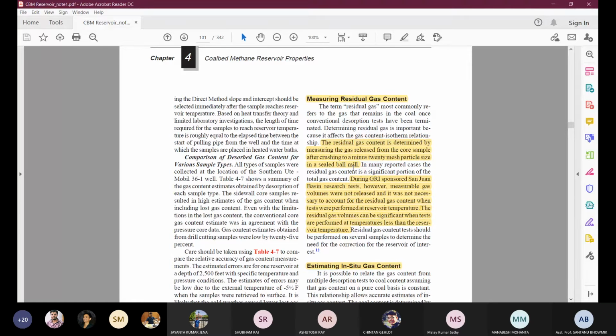So I hope you can understand. The minus 20 mesh size means the undersize of the 20 sieve, US mesh number 20. I have shown you earlier what the mesh number is, and undersize means the lower part, the smaller size fraction. There is the undersize, there is the oversize, so you have to collect the undersize.